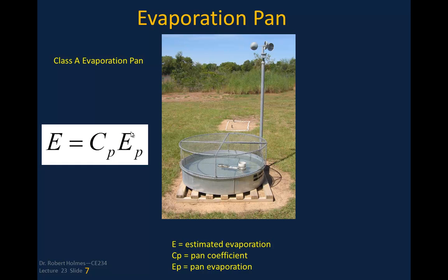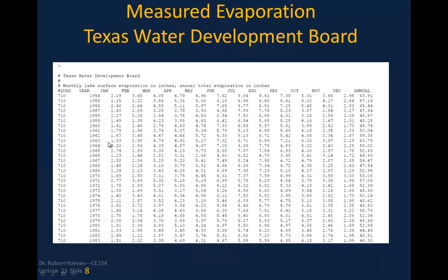And then you'd have a pan coefficient, which would be determined experimentally, well, actually through numerical models, because you have additional evaporation due to losses from the surface on the sides, so your pan evaporation would be different than what you would actually have for an evaporation, say from a lake or a much larger body. So that's using the pan evaporation data.